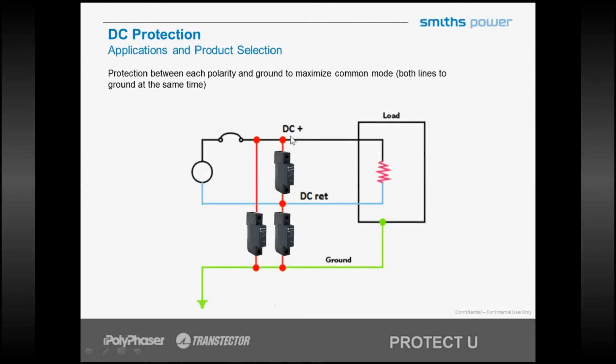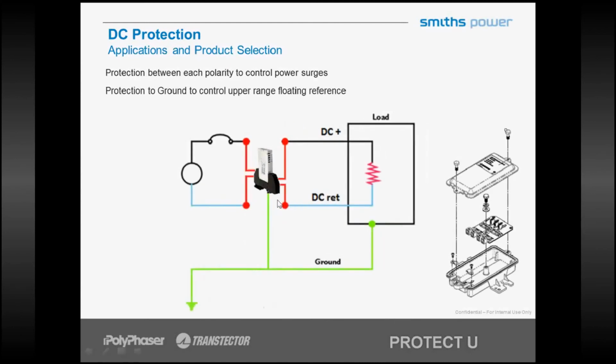In this case, this would be considered 3-mode protection. This is a very common type of protector in our product line. Our DC Defender employs this 3-mode protection. Here you can see our DRDC product being used in a very similar 3-mode protection. Each circuit is protected in series with our device, providing additional voltage control and isolation between the surge environment and the protected load, along with a reference to ground.